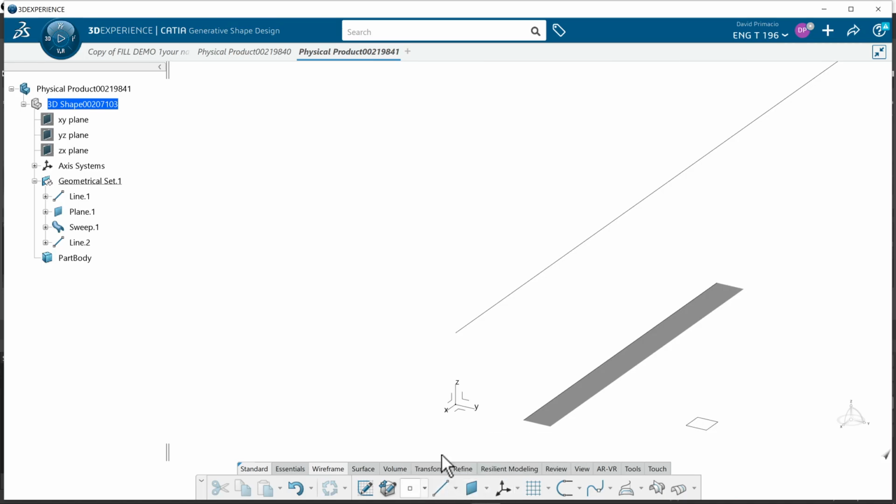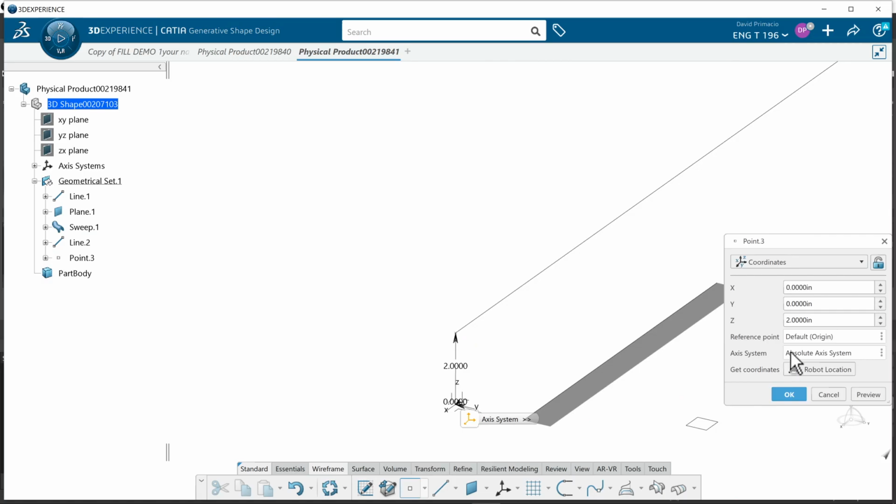I want to create a point. See if I can move this off so I can get to it. I want to reference that point. So I had to key in a number just to get that arrow away from it so I could actually get on that point. And the Z direction would be 180. If you're in Imperial Standards, you got to type in mm to get it to go to metric. Make sure Y and X are set to 0.